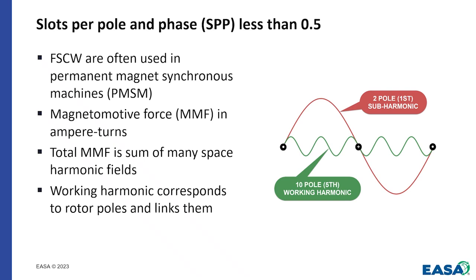And we can't see that by looking physically at the coils, but we can analytically come about it, on how it works and what it does. We sometimes see the negative effect of some of these space harmonics when we have problems accelerating a two-pole motor. Maybe we have a high fifth or seventh harmonic, and we get a cusping effect, a torque reduction as we're accelerating.